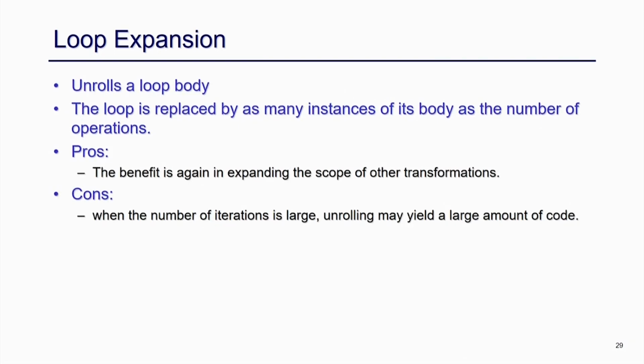So, sometimes we look for partial unrolling instead of unrolling the whole thing. As I mentioned, if your loop is running 3,000 times, I can unroll by 3 only. Then I am doing 3 operations in one loop body, and I execute the whole loop 1,000 times. So, I can go for partial unrolling if my loop iteration count is too high. You should always think about a trade off between the code size versus the controller size, or the kind of benefits you are going to get from loop unrolling.